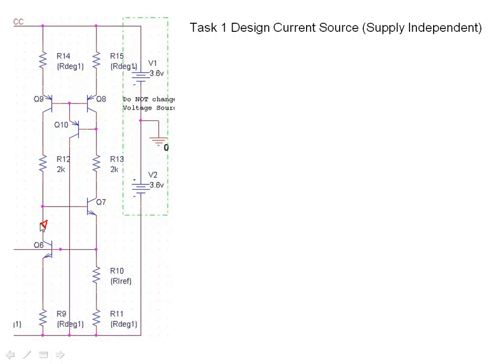We're going to want a reference current down here of 0.5 milliamps. According to the reference current design, there'll be 0.5 milliamps down here as well. We've got 1, 2, 3, 4 degeneration resistors that are going to improve the performance of this circuit. Well, let's just go back to our bit of maths. VAF effective is equal to VAF into 1 plus VT over VE. Now in this case we know that we want a 10 to 1 ratio, so VAF effective should be